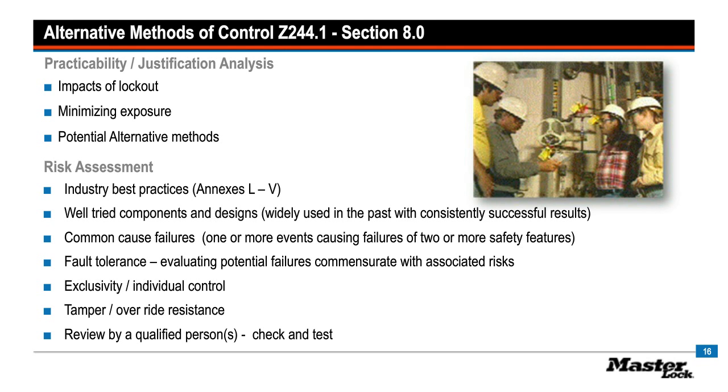from the consequences of sudden startup. And the alternative method risk assessment also requires review by qualified personnel. We want multiple eyes on what decisions are made. It shouldn't be a unilateral decision by the guy doing the job or the gal responsible for safety. There should be a combination of what operations says, what the machine experts say, and what plant engineering has in terms of contributing to this risk assessment process.